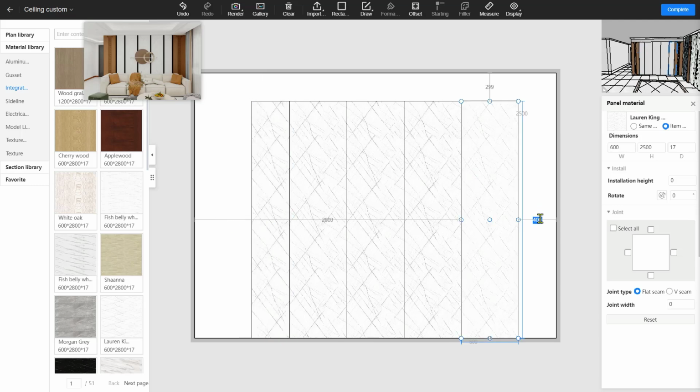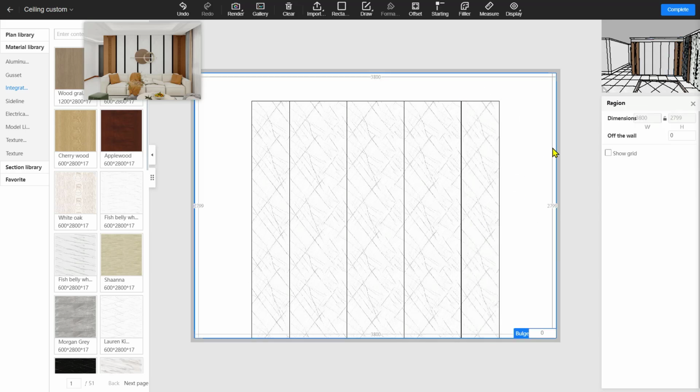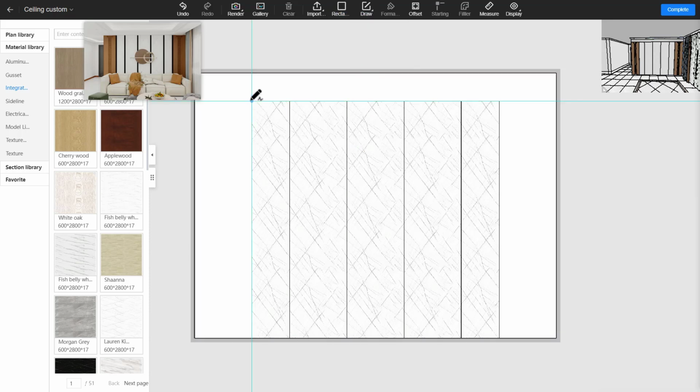And this is all still the same operations. 400, and this is 600. So now I'm placing this well. I'm going to draw this black line and going to the upper part to place some light between them first. So this drawing method, polyline: find the start point and end point, right click to disconnect. Start point, end point, right click to disconnect.